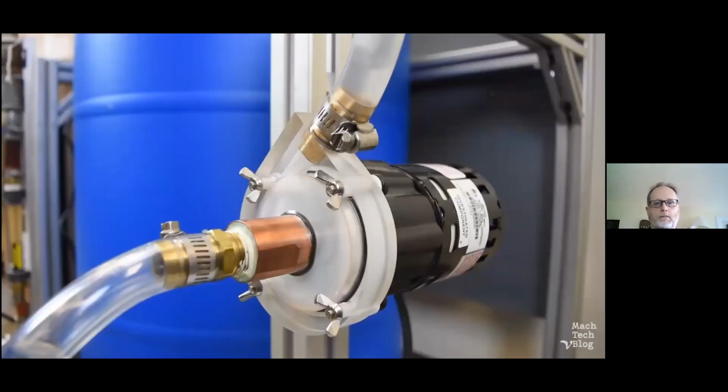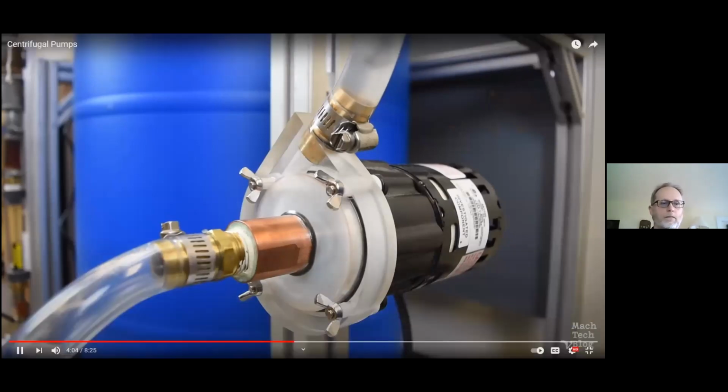It's important to add that because of the way that centrifugal pumps impart energy to fluid, the impeller must always be fully submerged and in direct contact with the pumped fluid. As we can see from this little light-duty pump, a centrifugal pump will not pump air, and it will not suck fluid through piping like a straw. We talked about this with hydraulics, the need to ensure that there is prime against the inlet of the impeller.